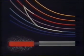Original. Let's see what that means in terms of the familiar property diagrams. Isothermal compression. Compression along an isotherm. Adiabatic compression. Temperature increase to another isotherm. Isothermal expansion. Expansion along this upper isotherm. And finally, adiabatic expansion to bring the temperature back to the original isotherm. And so on.